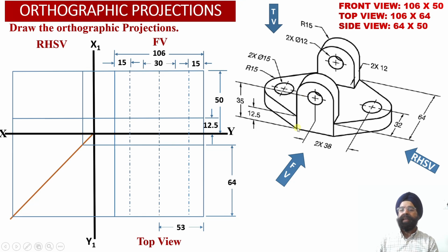Now we know that the width of this vertical web happens to be equal to 30 millimeter. Where from have we obtained this width of the web equal to 30 millimeter? Because we have been provided with the information that the radius of the semicircular web happens to be equal to 15 millimeter. So this diameter becomes 30 millimeter. So the two vertical edges of the vertical web will be separated by a distance of 30 millimeter from each other, and this is symmetrically located at the center.